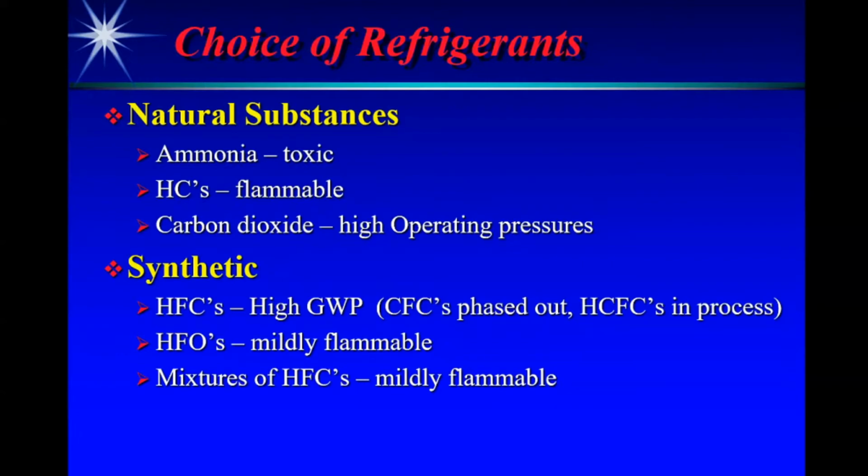Carbon dioxide has also been used in several systems. It may not be the best refrigerant in terms of energy efficiency of the system, but it is a natural substance. The other major issue with this is the operating pressures tend to be very, very high, especially in countries like India, where the ambients are very high. The operating pressures become too high. It could be approaching something like 80, 100 bars on the condenser side, and therefore safety becomes a concern.